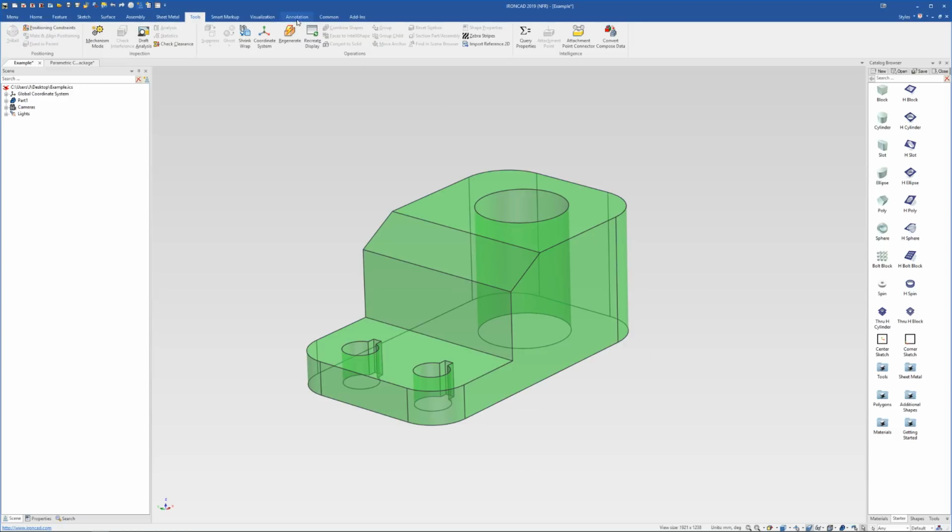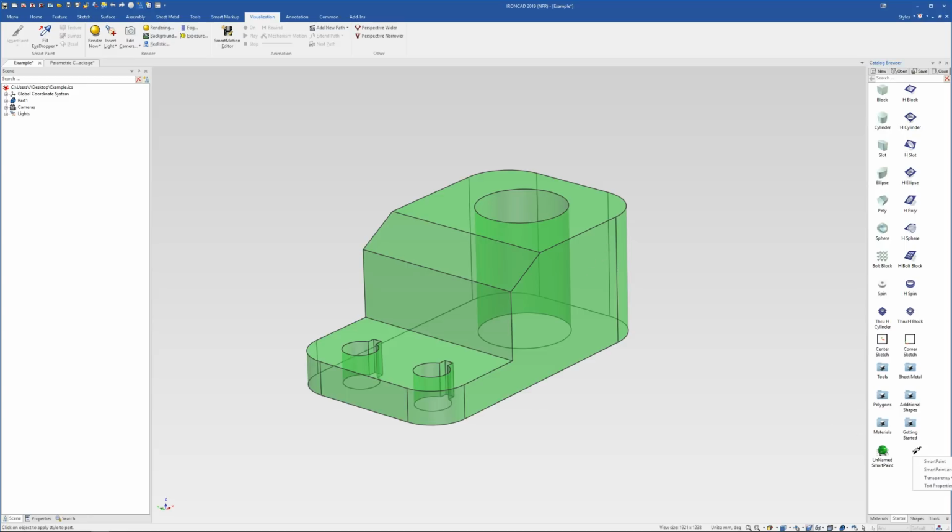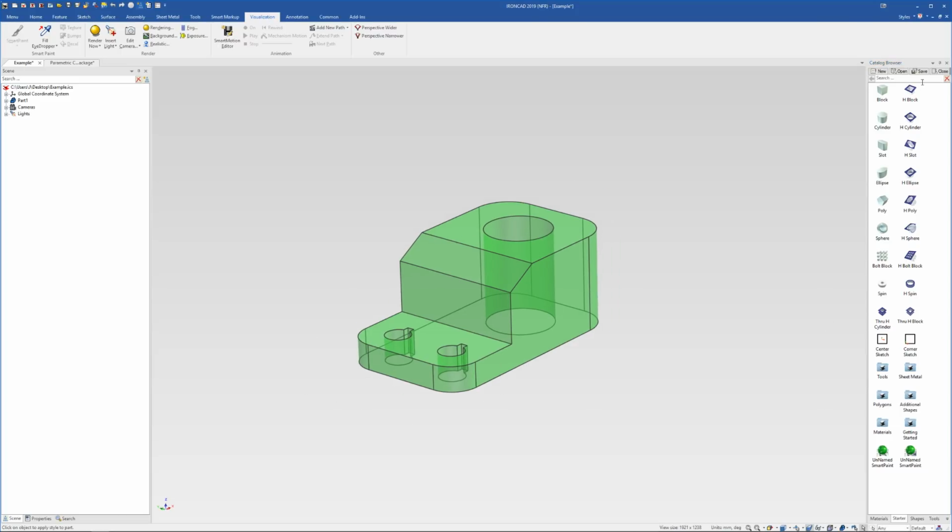Now, if I go to the Smart Paint tool, which is up here, I can go to the Fill Eyedropper. If I click on that, it's going to fill it. You can see the little tool filled up there. And if you click into the catalog, it's going to place that paint. So it paints other products the same color. But if you right click, you can paste the Smart Paint and the material. That way, you can see it's got a little M next to it now. That way, it'll actually copy the material properties as well as the color properties.